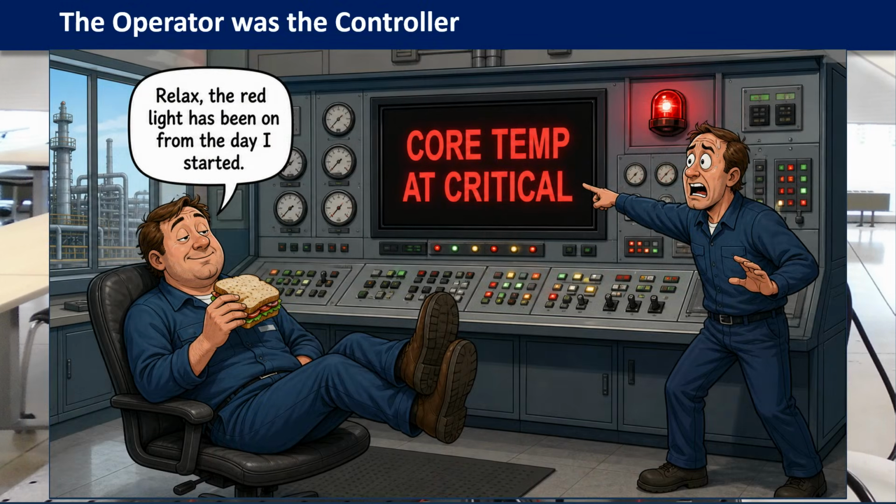These early instruments represented an enormous improvement, but they only provided information. The pressure gauge could tell an operator that steam pressure was rising. It could not decide whether the pressure was too high, and it could not adjust the process. The operator had to read the gauge, decide what the indication meant, and then manually reduce the fire, adjust a valve, or take some other corrective action. The instrument measured. The operator decided. The operator's hands controlled the process. In other words, the feedback loop already existed, but a human being completed it.